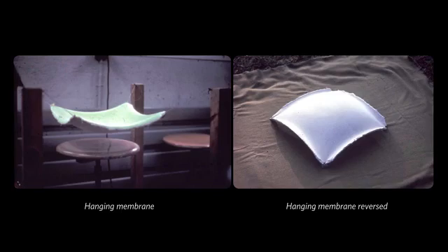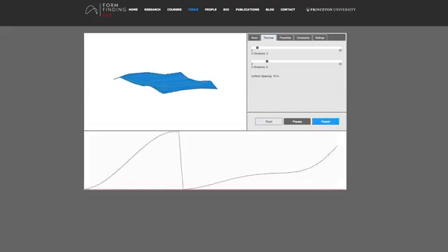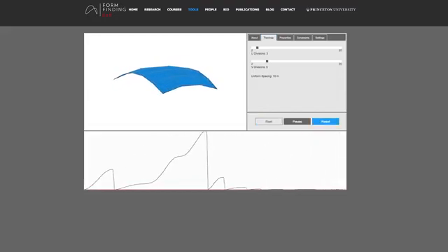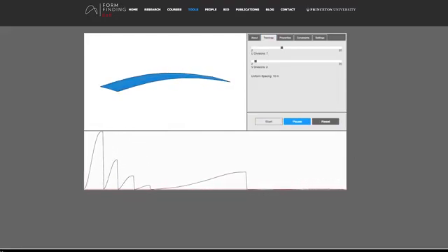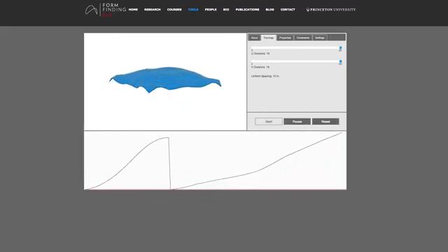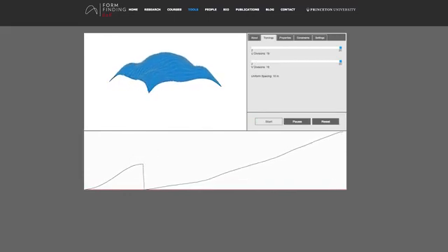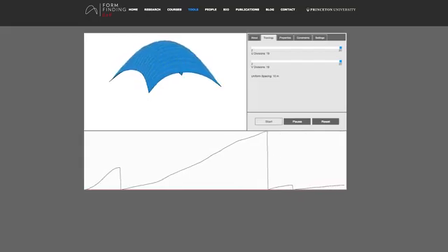Building such a physical model is time-consuming, does not provide all the information the engineer needs, and is difficult to share with clients and architects. We can now generate many ideal vault shapes on the computer without having to build physical models due to the development of form finding and shape optimization tools. The form you see here being generated is based on the same process Heinz Isler used, a hanging cloth model. Only the form here is generated on a computer and does not use a plaster-dipped cloth.